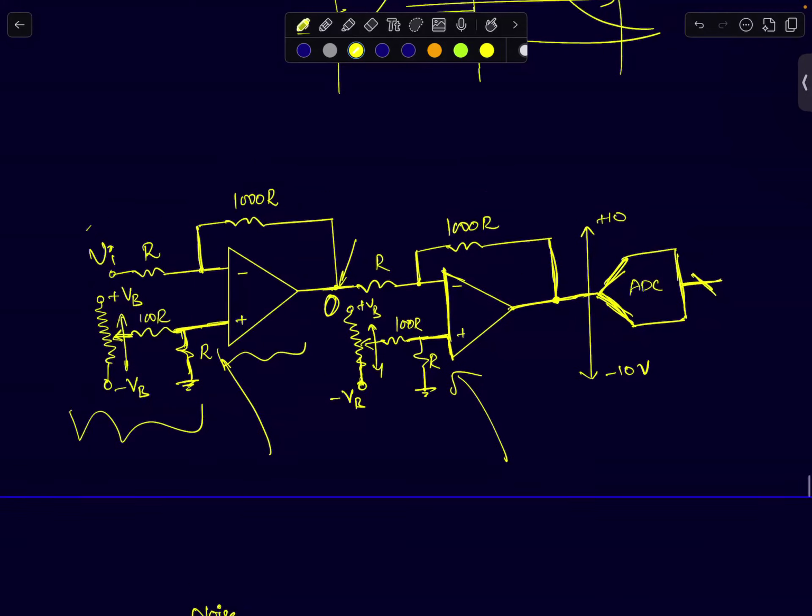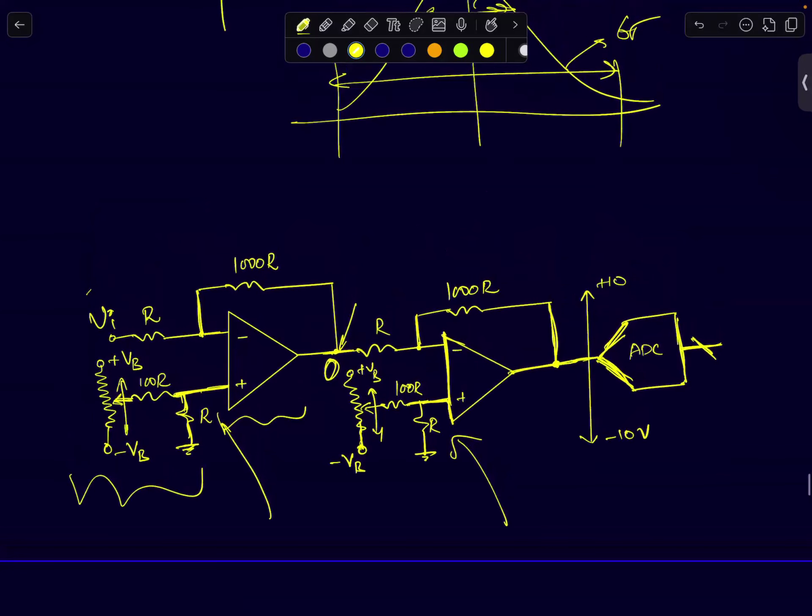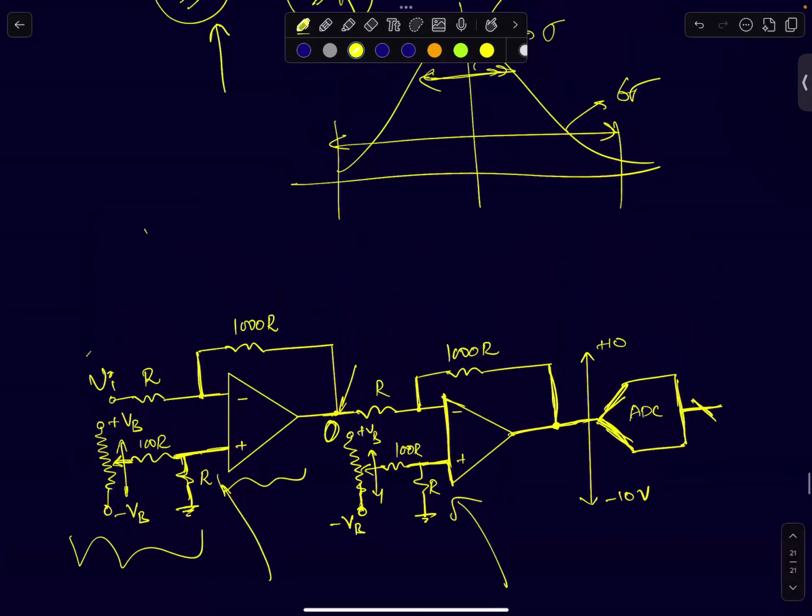One thing that I missed in this lecture is that offsets, we just treated like a constant voltage, which is not changing. But in practice, offsets will be functions of temperature. As you vary your temperature from some minimum to maximum value, your offset voltage will also change.